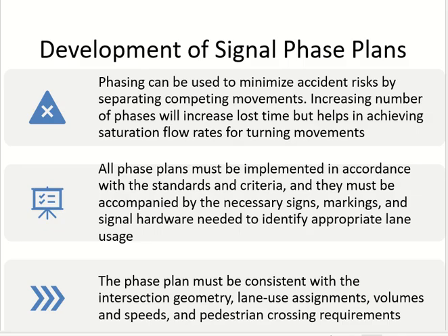And then the signal itself. If there is a separate signal for left turning, I should see a separate light, which is only for left. So you need the marking, you need the lane, you need the signal, and then you may need the direction signs as well, to show people where they can go and so on.